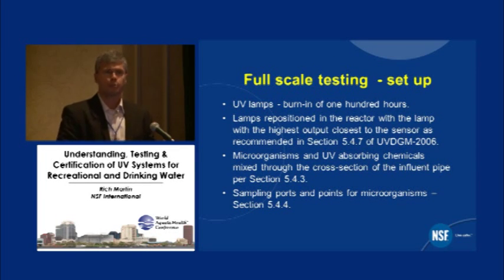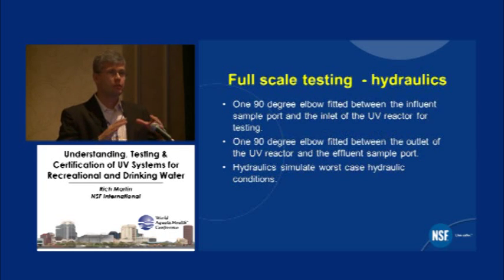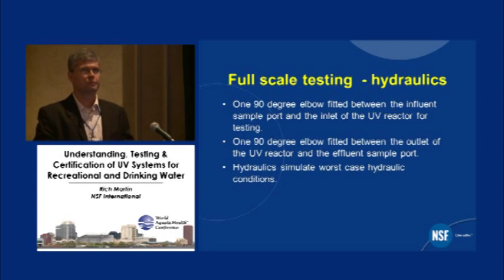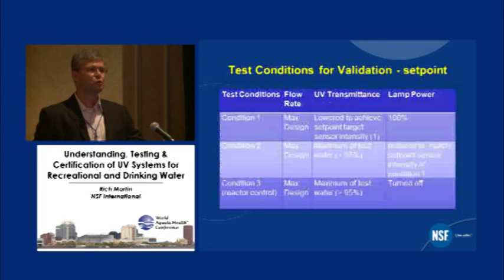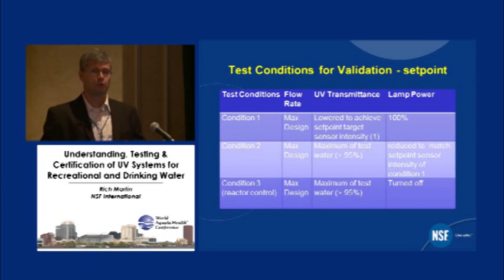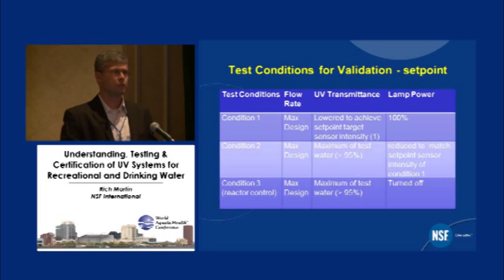Good question. I'll just repeat the question. Because of the 2010 change to Standard 50 incorporating testing and evaluation requirements for cryptosporidium, does that somehow remove or supersede the requirements that have been in the standard for years, the 3-log kill for Pseudomonas and Enterococcus? No, it doesn't.